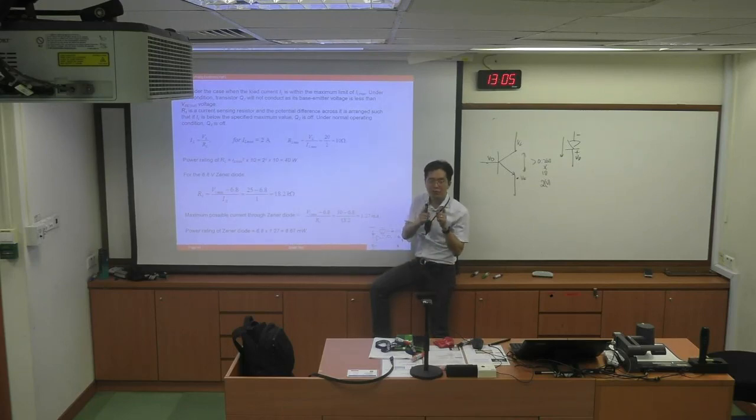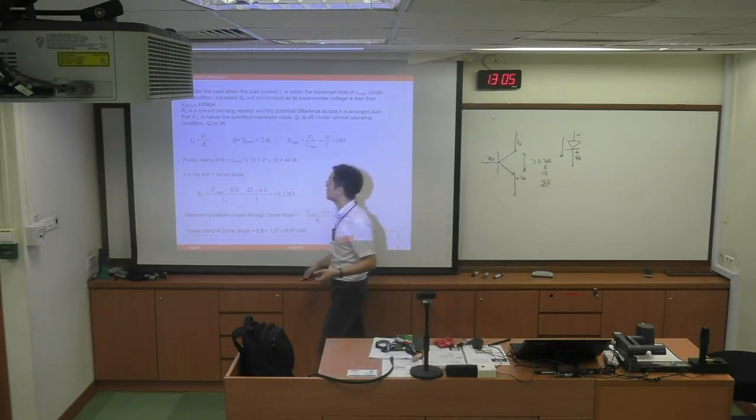That's where the output protection circuit should be there, because while you're working, for various reasons such as wire insulator failure, or sometimes you accidentally connect the load output directly to ground, a short circuit to ground. In those cases, you need to make sure that the regulator cuts off by itself so you don't overheat. So that's why the protection circuit is needed.